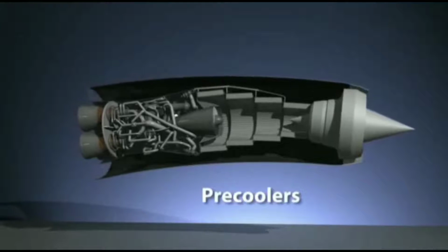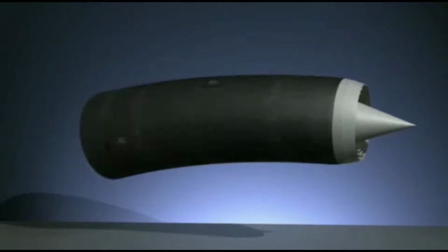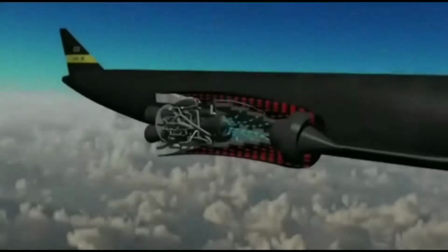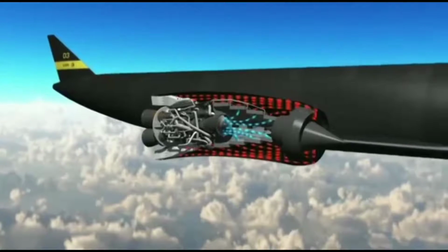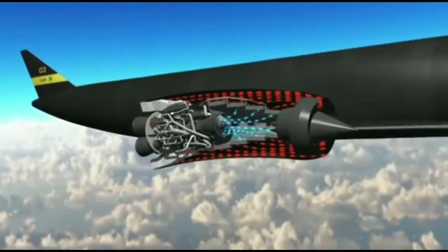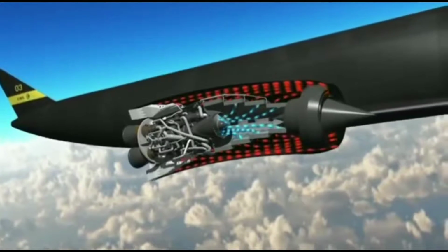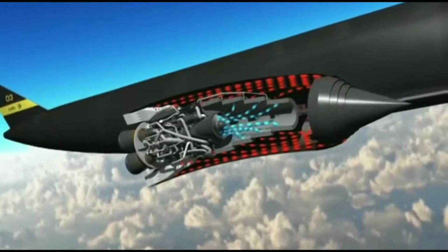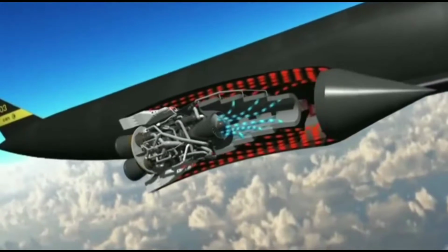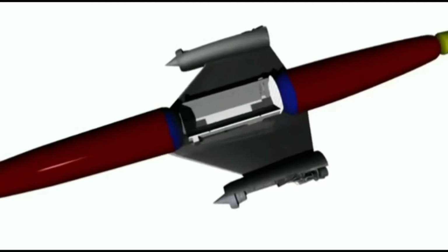In air-breathing mode, the turbocompressor with the lightweight air pre-cooler is positioned just behind the inlet cone. At high speed, the pre-cooler cools the hot compressed air, which could reach a temperature that could not be withstood. The compressed air is then fed to the rocket combustion chamber, which is ignited with another propellant called liquid hydrogen. This high pressure ratio provides a high thrust.